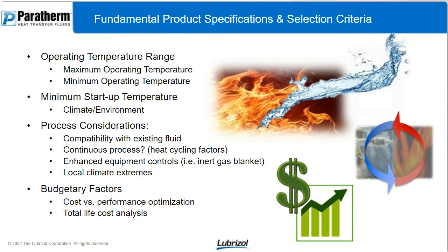If you're in an area where you need 550-degree operation, but when you fill that system and go to start it up, or if you do maintenance and go to restart the system, and you're in a cold weather environment, in negative temperatures or really low temps, you need to make sure that you have a fluid that's able to perform under those low temp startup conditions.